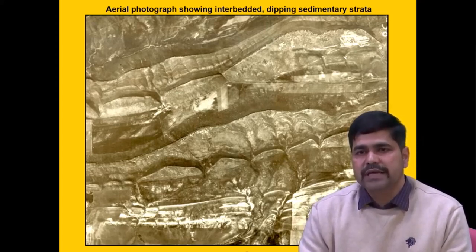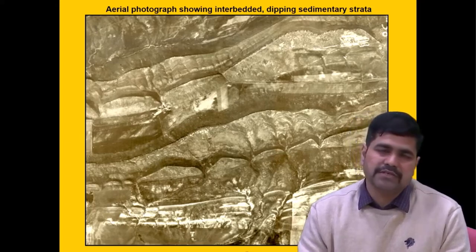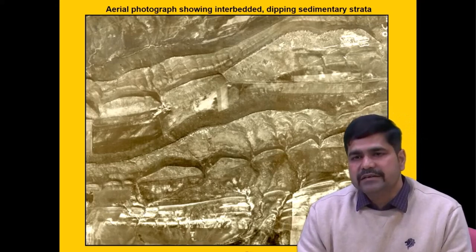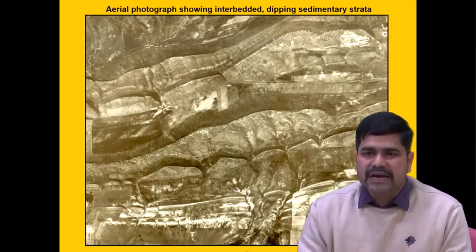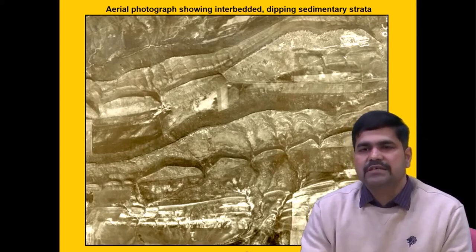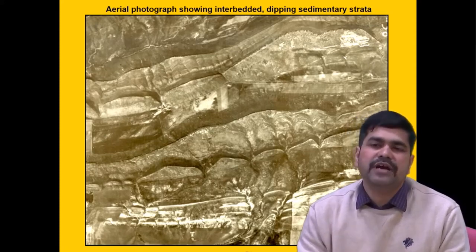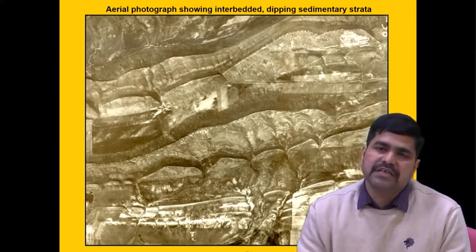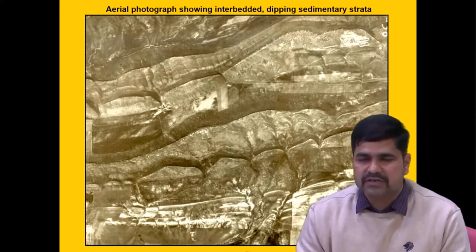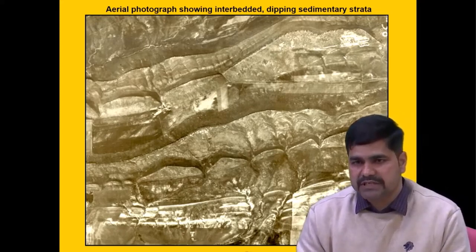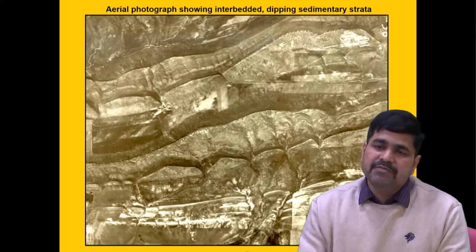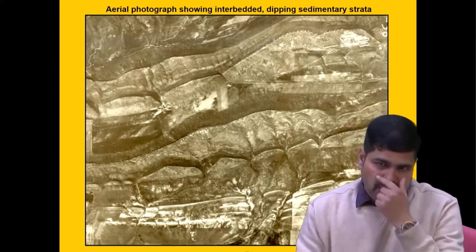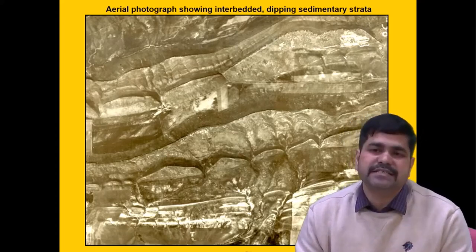Now, what all things can you derive from this photograph? Can you see a general trend of the bedding? Bedding means simply where the lamination is dipping. Can we search for that? From this image we can see the basic strike lines of the beds present in this region. What is the basic dip direction? Is there any fault or fold axis? What are the joint sets present?